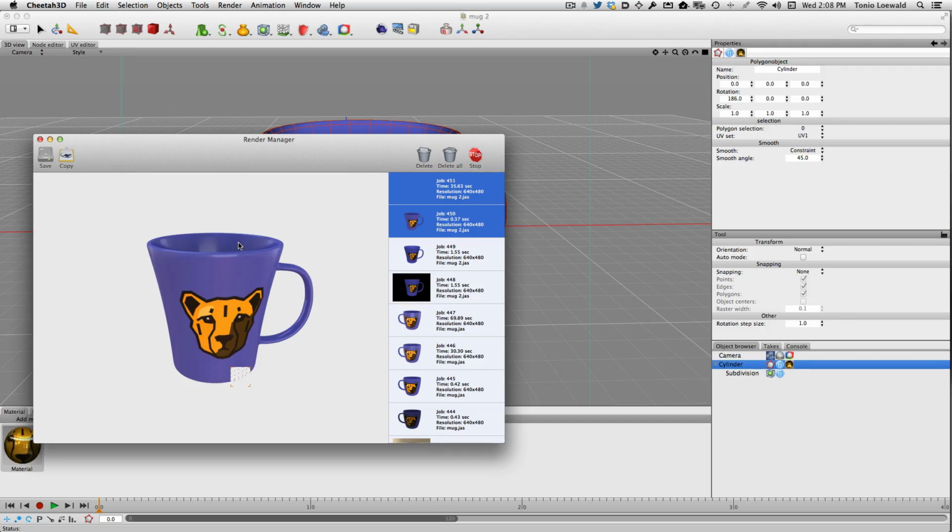So a couple of takeaways here. If you want to create a nice render quickly, having a nice HDR to play with is a really good way of getting renders that look great and are fast. And if you don't have one, then Skylight is also a pretty good way of getting a render that looks pretty good and fast. The real problem with Skylights is that if you want reflections, you have to turn on geometry, and the geometry also renders in the background for some reason. There's no option to have the geometry visible in reflections but not in the background. And the geometry for Skylights looks good in reflections but terrible as a background. There are some ways around that which I get into later in the book.